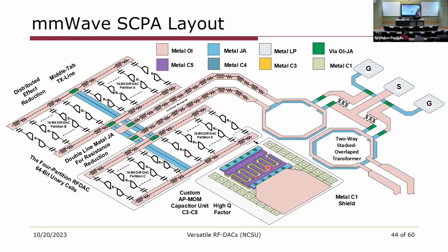I think I missed, why are you using IQ combining here and not earlier? In this case, we were trying to use really wideband signals, and with polar modulation, you have to do a conversion from Cartesian to polar that ends up with really wideband signals. We normally need something like 10x the bandwidth. We're trying to do 400 megahertz signals, so it would have implied that we need 4 gigahertz bandwidth in our amplitude path and phase path. Yeah.